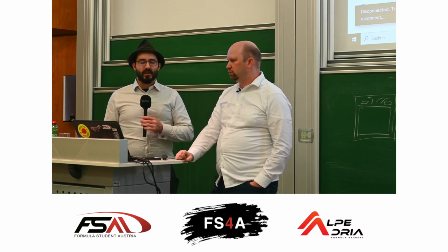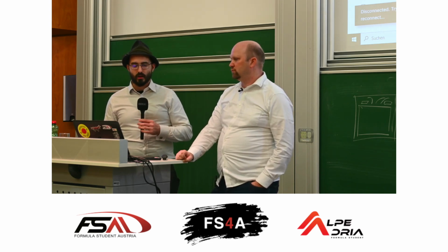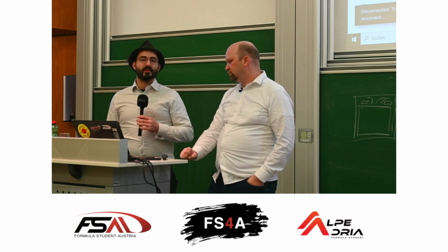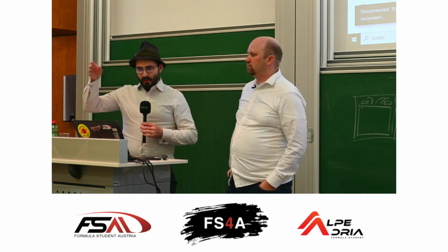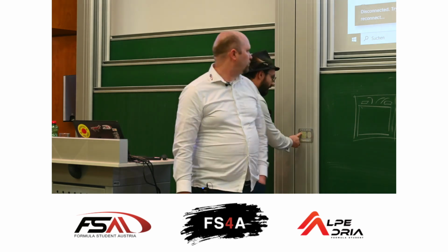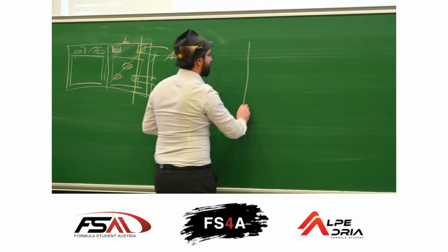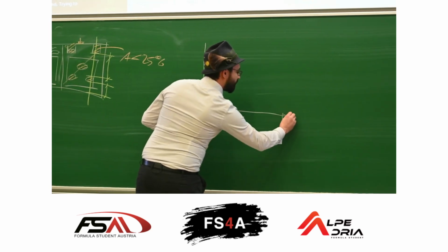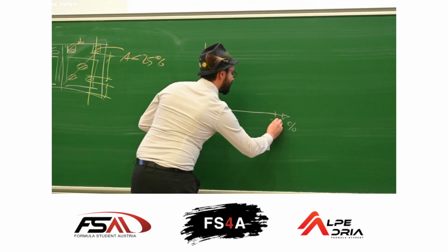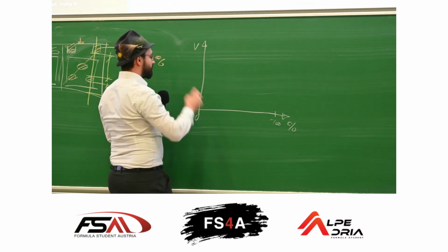Answer is a clear no. It says you need to have two signal outputs which have non-parallel and non-intersecting variables. We're talking about two sensors. You have your throttle position in percentages from 0 to 100, and you typically have your voltage for the sensor.